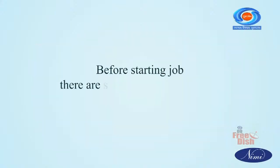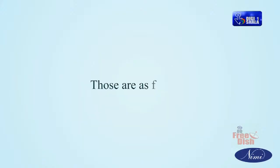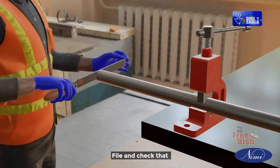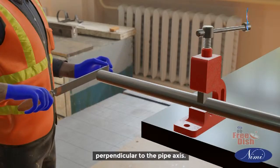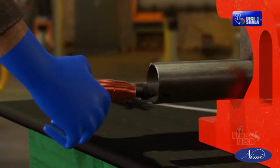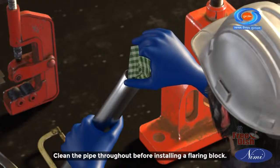Before starting the job, there are some preliminary checks to be made. Those are as follows. Check the material size and its condition. File and check that the end of the pipe is exactly perpendicular to the pipe axis. Slightly deburr the inside and outside edge of the pipe. Clean the pipe throughout before installing it in a flaring block.